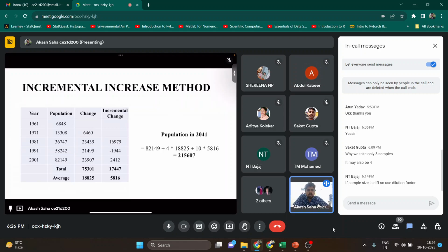It depends on how much recycling you are doing, right? Suppose in the Indian context also, they have defined type A, type B, type C, type D water. For each type there is a discharge standard. There are guidelines, like we will say it is type A or type 1 water if it maintains this much of BOD, this much of COD, this much of microorganisms, this much of heavy metals.